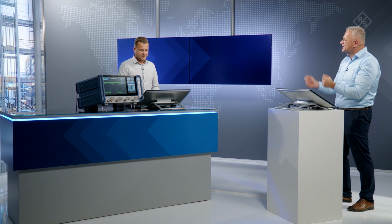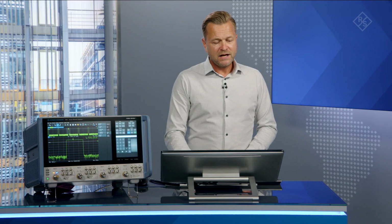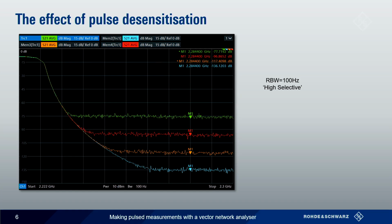What's the challenge there? Yeah, so if we think about a basic bandpass filter, I've got a picture here which shows a filter response where we've overlaid various memory traces of the measurement at different duty cycles. So the first one here, if we look at 100% duty cycle, that's of course a continuous CW signal, so there's no reduction in power due to pulse desensitization. And in this example, we have a noise floor of about minus 135 dB.